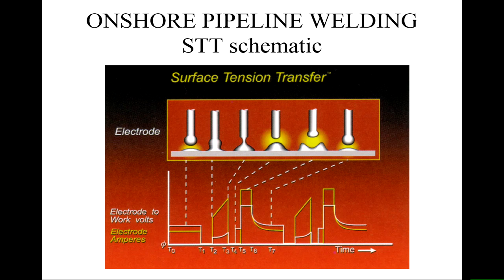So we've got a welding supply that can stop and start the current supply instantaneously. And that's really what you get when you have digital power supplies that are available. You couldn't do that where you had to wind the power up and down with an old-fashioned transductor power supply that was used for welding in the past, for instance. But with these modern solid-state systems, you get much more control.